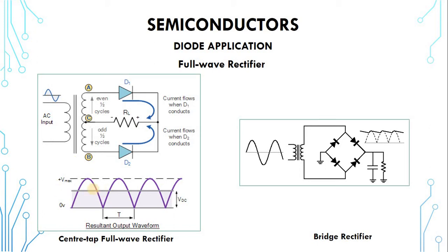So it begins to discharge the charges that it has stored in the form of electric current. It begins to discharge it to the load. So now from here, the load does not take from the rectifier again, it begins to take from the capacitor. So the capacitor now begins to discharge gradually. The discharge of the capacitor will usually not drop just like the way the one from the rectifier drops. So it will take a longer time for it to drop to zero.